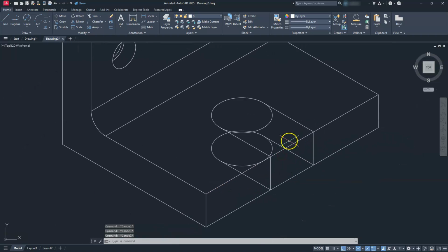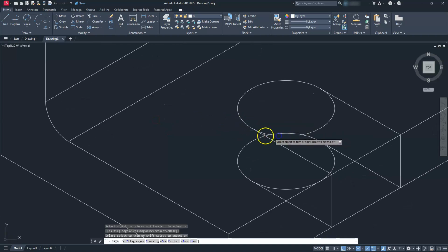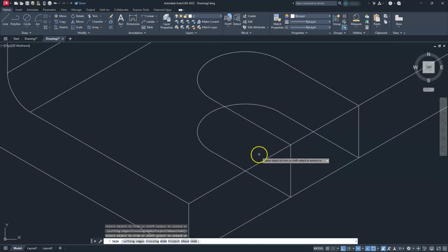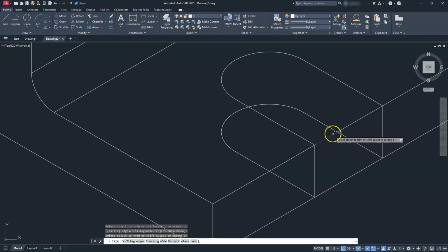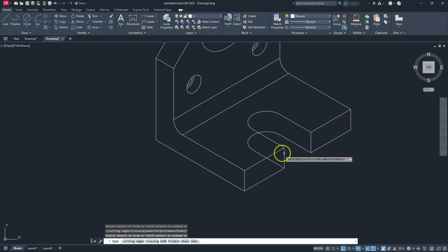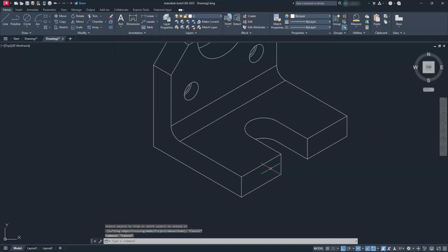Okay. Last thing I need to do on this portion here while I'm creating this is go ahead and start doing some trimming, right? So kind of like I did with the beginning part, I'm going to get rid of this arc that's going around both of these first. So that arc is gone. And let me zoom in and get rid of the rest of this arc that's running around here. Okay. Next thing I'm going to do is get rid of this line here in the middle, since we won't see that. And then we start looking at what we're going to see happening here. Well, we don't see anything that's on this side. Okay, it looks like we have that created.